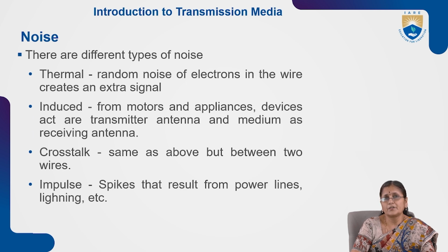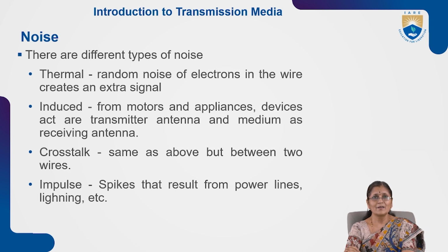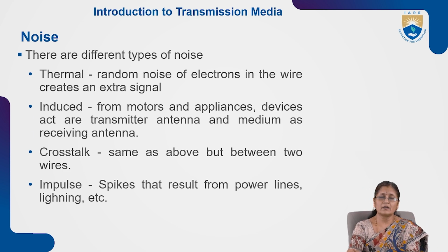Then the induced noise. What is induced noise? When the signal is going through the medium, other noises are added. Motors, appliances, any devices we are using act as a transmitting antenna, and whatever medium we are using itself acts as a receiving antenna.